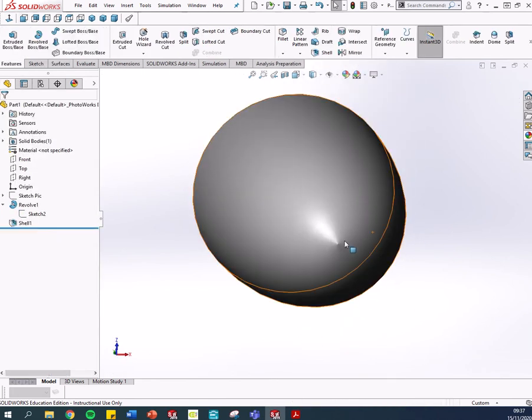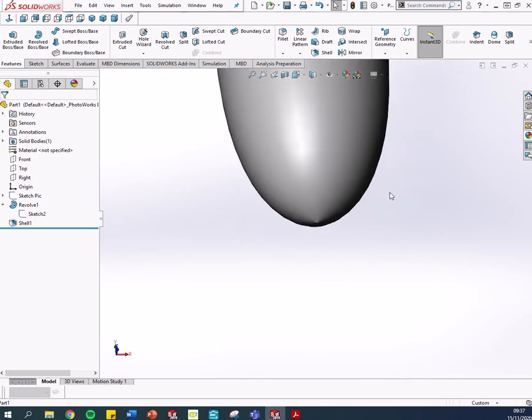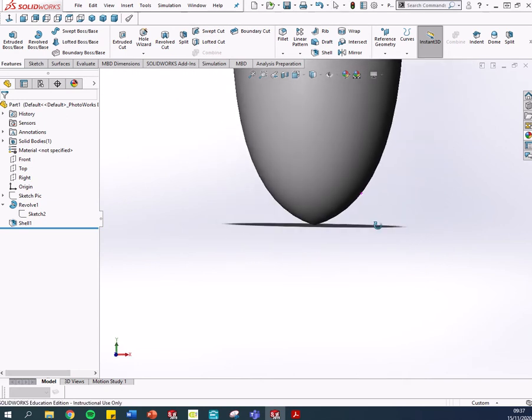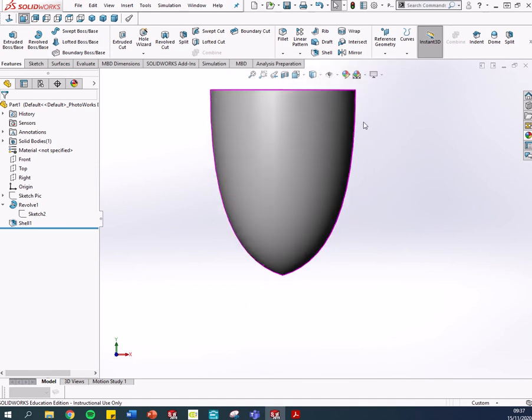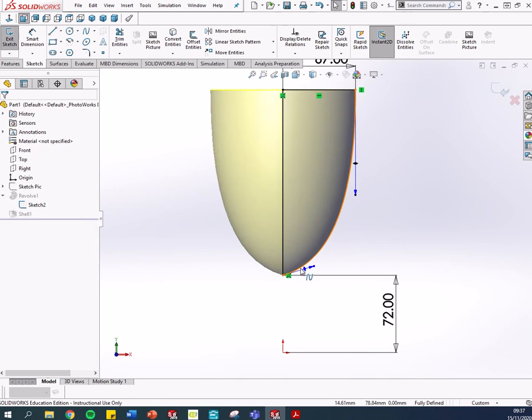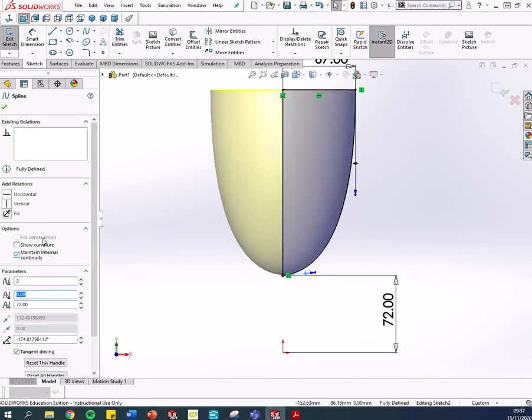Now see the way it has a kind of a point on it there? We ideally want it to be nice and smooth, and to get rid of that, anywhere there's an axis of symmetry or a revolve, an axis of rotation, we try our best to make the spline handle of a spline be perpendicular to the axis of symmetry or axis of revolution. Okay, so in this case I need to make it horizontal, so we'll be doing that quite a lot.